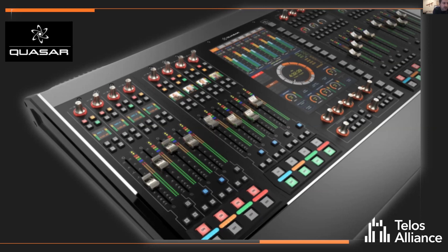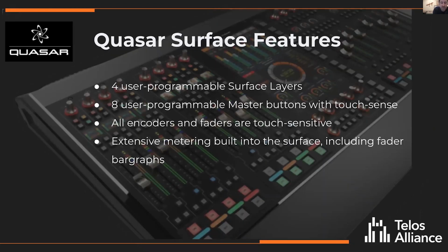Yeah, many customers on here will already be aware of how layers work. You're familiar with it in a lot of television broadcast consoles or consoles that are designed more for the pro sound industry. So layers essentially are, if you think of consoles, faders that are stacked on top of each other, and you're turning pages in a book. So your first page has got 16 faders, and when you turn that page, those first 16 faders are still doing their job. You just now have the ability to look at 16 additional faders. So we have 4 layers, and you can switch very quickly between any of those 4 layers. The faders here are motorized, so they'll snap to position of those layers. And really for an 8 fader console, 8 physical fader console, you have the ability to really control 32 faders.